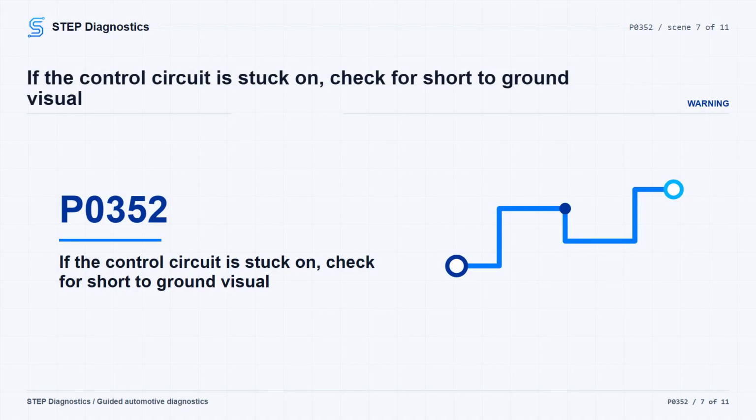If the test light stayed on constantly, isolate the coil 2 K17 control circuit and check it for a short to ground. The ignition must be off when checking continuity to ground.